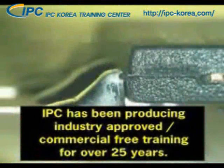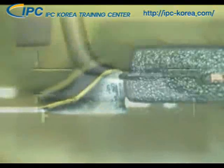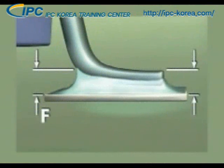As an exception to this rule, solder may touch the body of plastic SOIC or SOT components. For dimension F, the minimum heel fillet height should be at least as high as 100% of the component lead thickness at the toe.